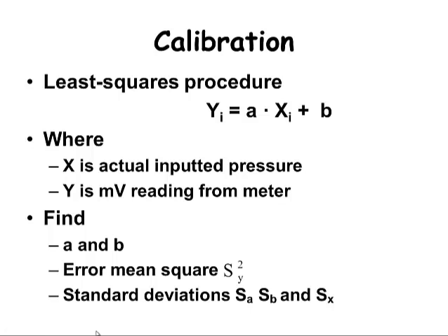There are 22 data readings from 0 pressure up to 10 kilopascal pressure. One set of data, 11 values, was collected by adding weight to the deadweight tester. The other set of 11 values was collected by removing weights on the deadweight tester. This was done to see if we could detect a hysteresis effect on the sensor. We will talk more about hysteresis later in the course.